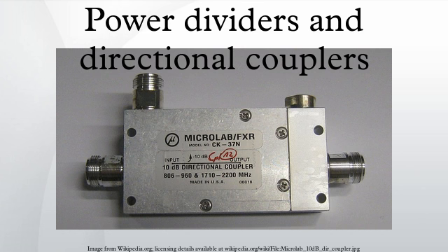Telephone handsets include such a converter to convert the two-wire line to the four wires from the earpiece and mouthpiece. Cross-connected transformers. For lower frequencies, a compact broadband implementation by means of RF transformers is possible. In Figure 17 a circuit is shown which is meant for weak coupling and can be understood along these lines.